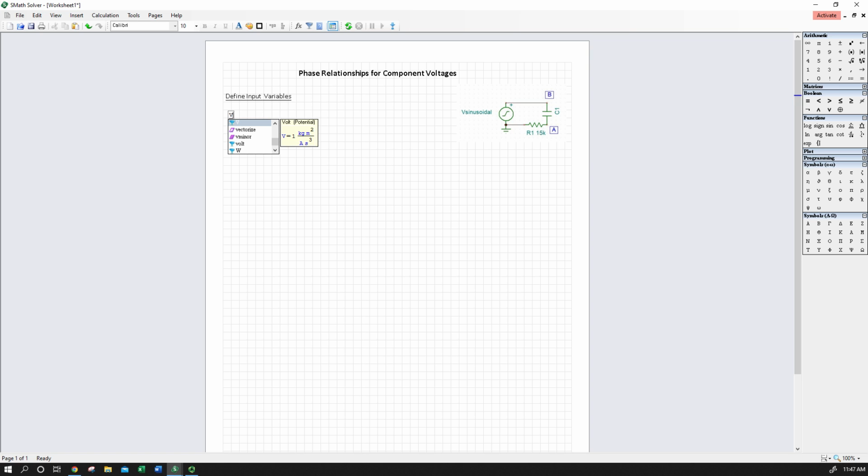Now, the way that we indicate a subscript in SMath is to hit the period. And because now I'm defining a variable, not just typing text, I'm going to use a different method of starting my input. I'm going to hit the colon, and you can see that SMath brings up a little equal. So now it's like, oh, we're going to define a variable, or we're going to put in a formula. So the double quote indicates text, or the colon indicates a formula.